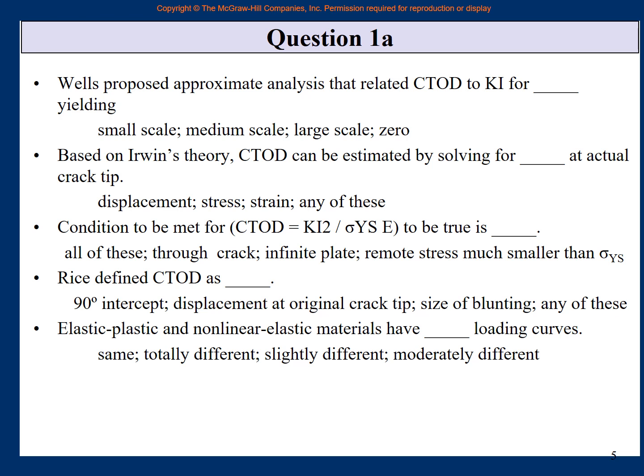You see, elastic plastic is standard: linear elastic and then curved plastic. Non-linear elastic is totally curved. But when you are loading, it is the same. When you unload, then in the elastic plastic, you draw a line which is parallel to the original straight line. But when it is the non-linear elastic, you go on the same curve. So unloading will be different for the two, but loading is the same. So that is the answer.